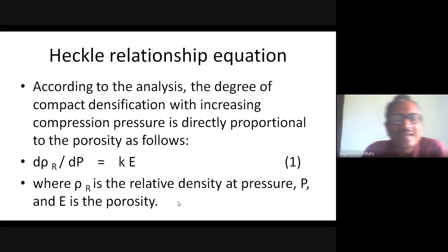How did you calculate the porosity? You take the true density minus bulk density, divided by the true density, into 100, and you get percent porosity. If you take it simply as a ratio, it is approaching 1, or less than 1, or greater than 1. That is what you have already got. If you have the highest porosity, the ratio will be very small.